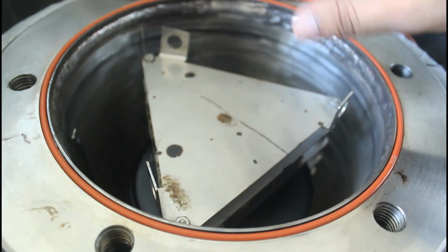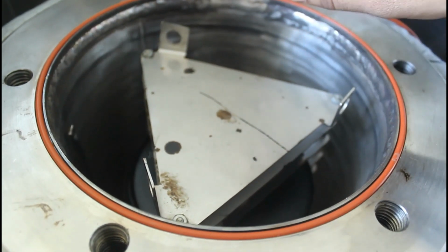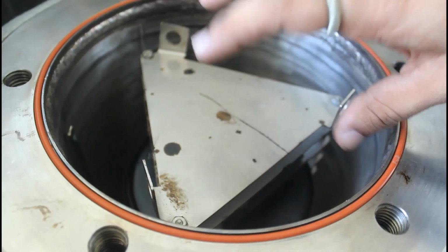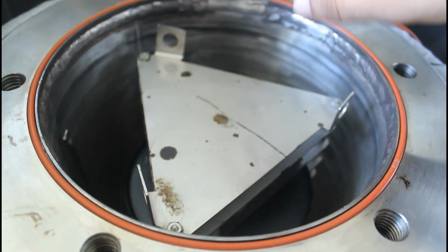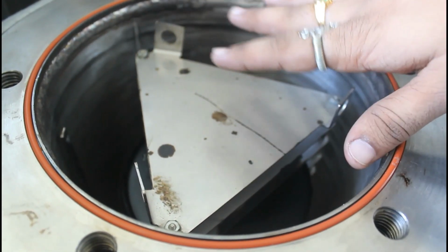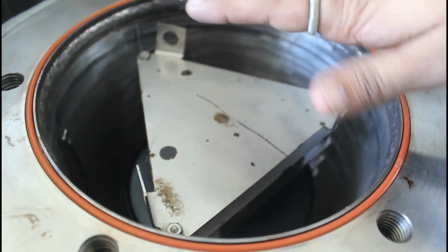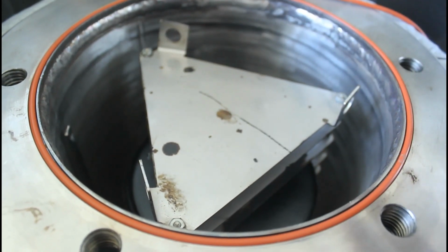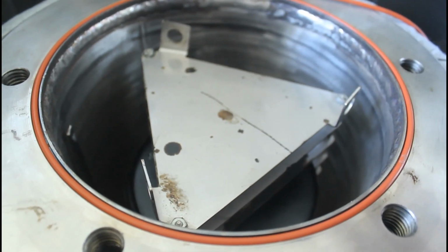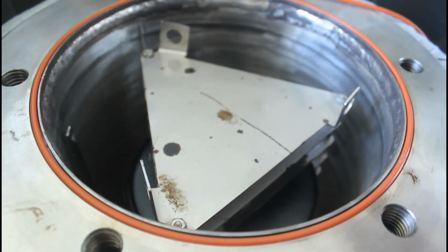Once you close this lid, we apply a pressure of 2.1 megapascal and set a temperature of 90 to 110 degrees. In that range you allow it to age for at least 20 hours. So for 20 hours the bitumen is subjected to a temperature of 90 to 110 degrees and a pressure of 2.1 MPa.